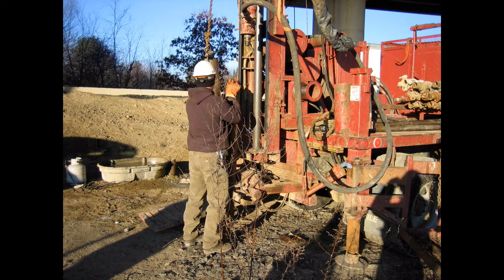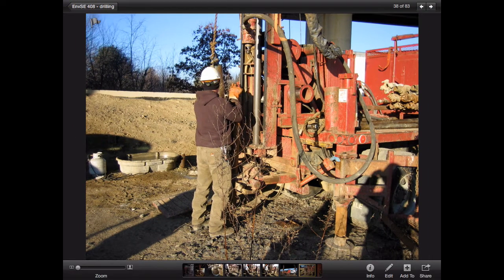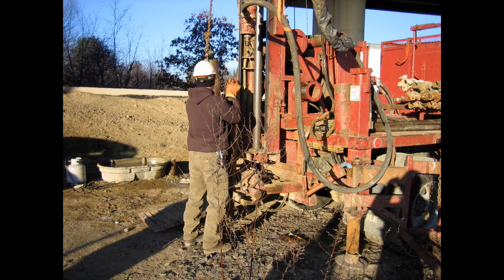Set up on hole. All the fittings, of course, are tapered, and so they don't lock. And so this tapered male fitting goes into a similarly tapered female fitting, and you never drill counterclockwise, for obvious reasons, right? You just unscrew all your drill string in the hole, and so you always drill forward. Even when you're retracting it, you're drilling it in the same direction.